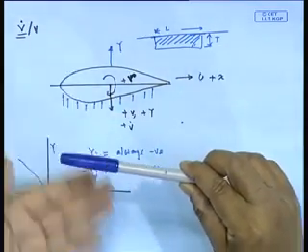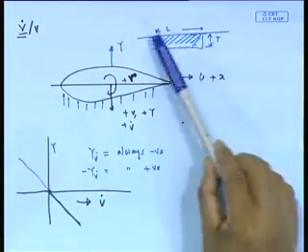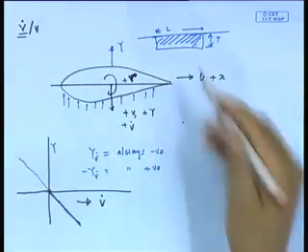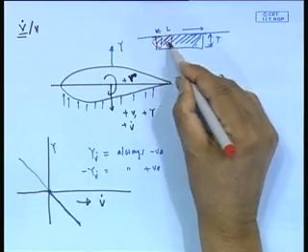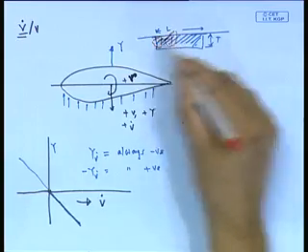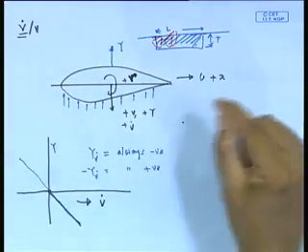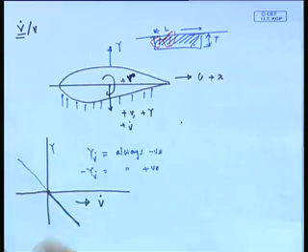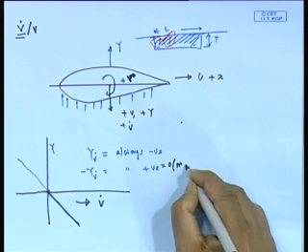There it will be the bottom surface pushing the water, here it will be the side surface, that is the T surface, the L by T, as if this much is being pushed. So, it is going to be essentially similar to the water mass of this semicircle, almost like this mass. That means added mass in sway is more or less of the order of the mass.